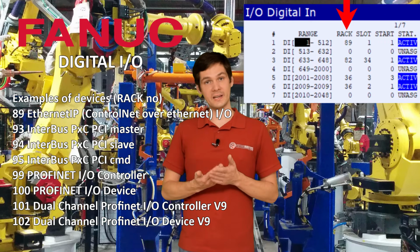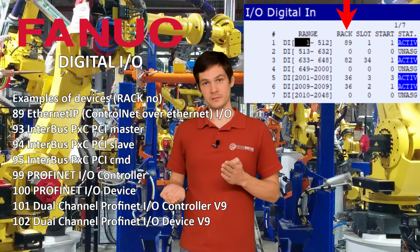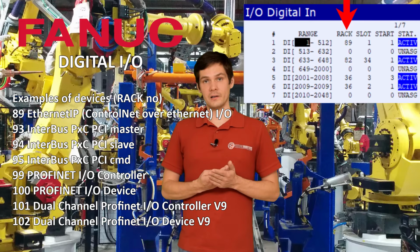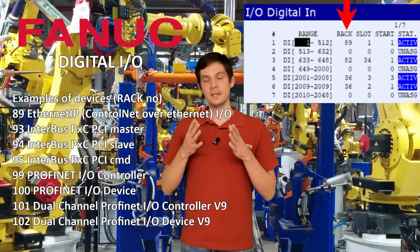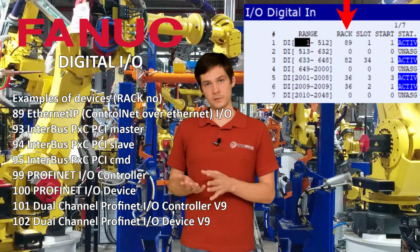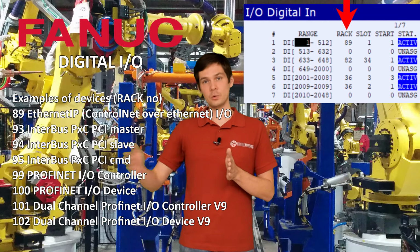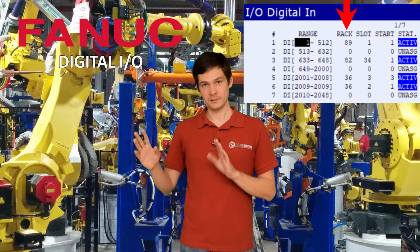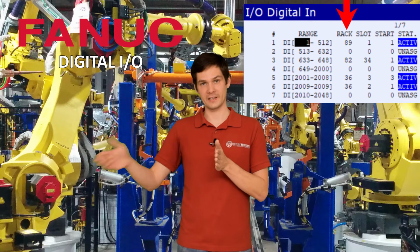If you put 99, that's going to be Profinet or DeviceNet. Anyway, the number tells the robot what card you're using. So we can imagine that the robot has like 200 different racks. Just imagine that there are like 200 places where you can plug a card.